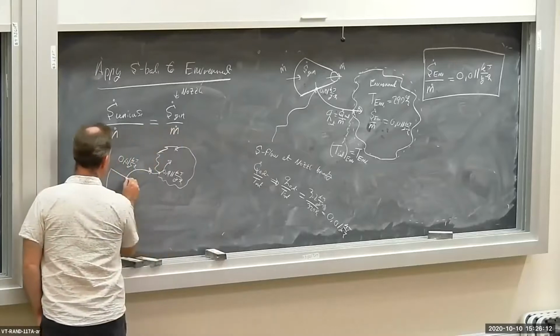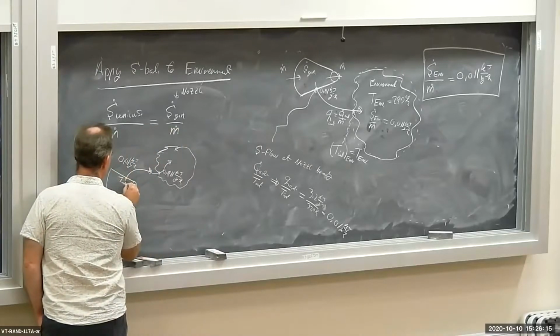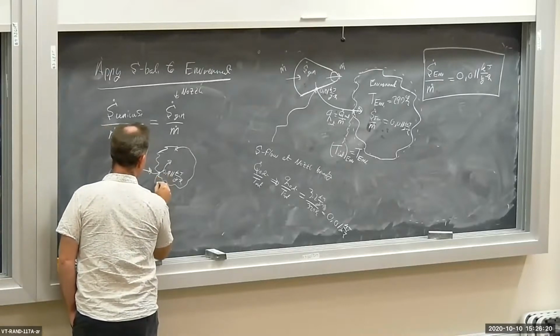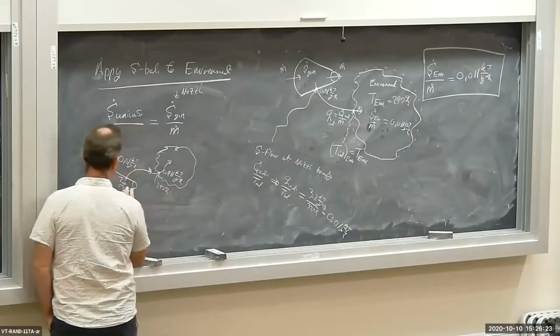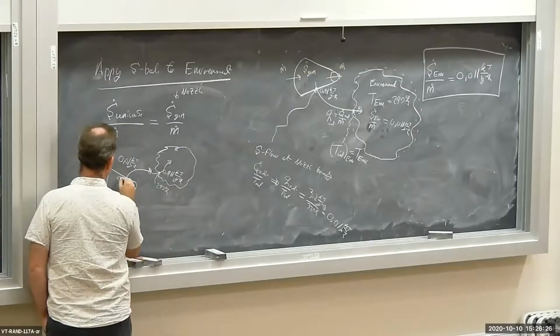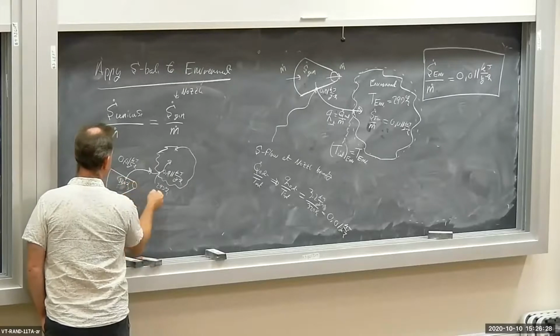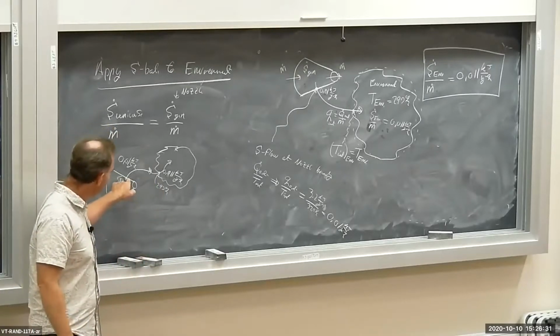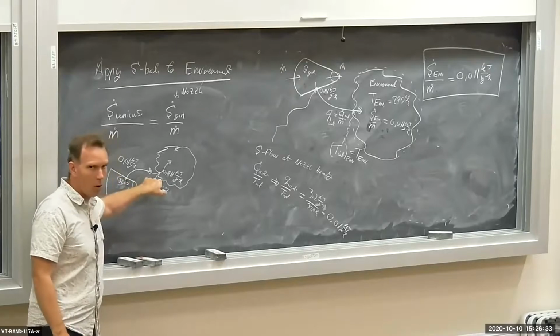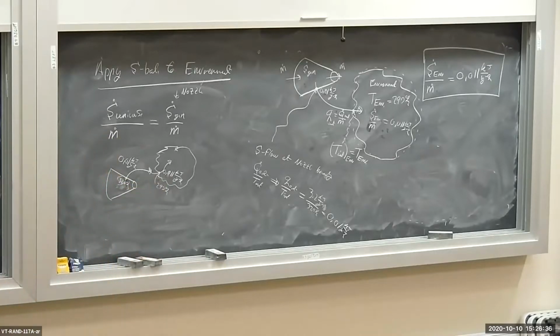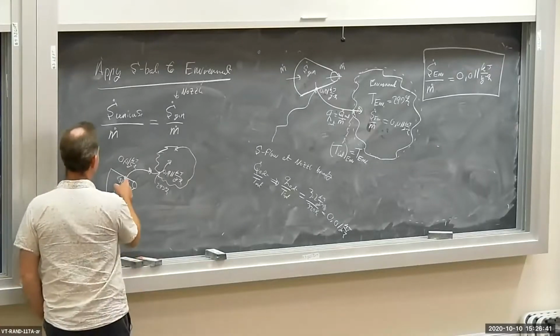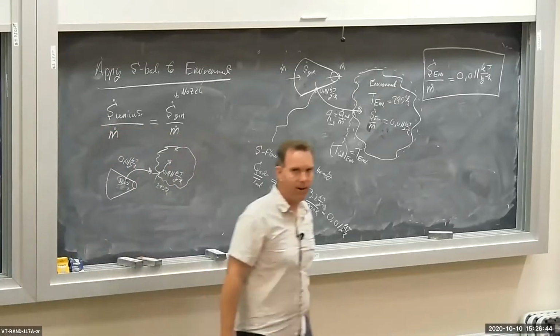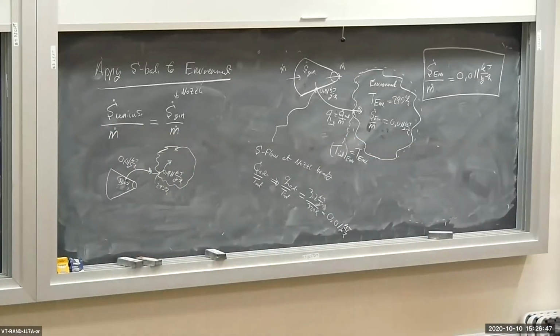The interaction temperature here is 320, and the interaction temperature right here is 293 degrees Kelvin. So 320 and 293. Heat is flowing from hot to cold. 320 to 293. Heat is flowing from the hot nozzle exterior to the relatively cool environmental boundary and then into the environment. Is that a reversible or an irreversible process?